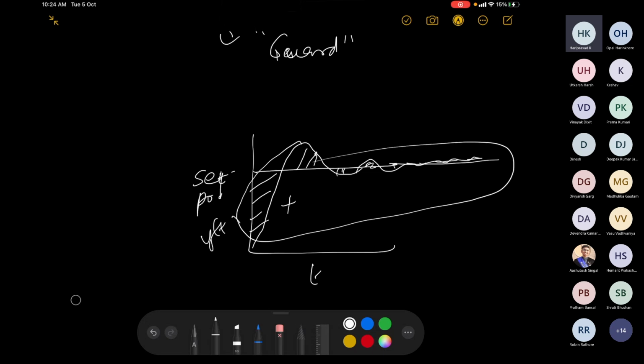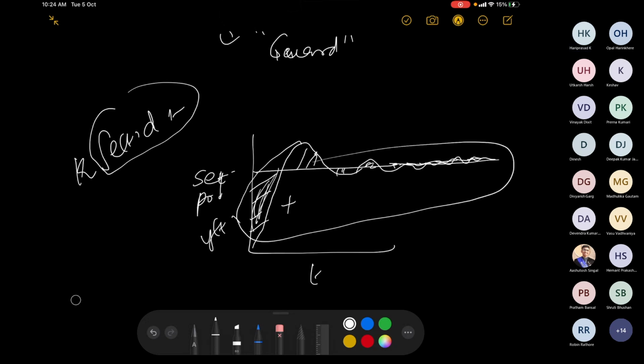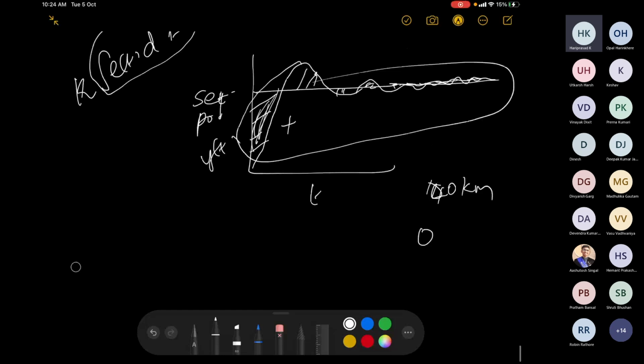So your control action is K times the integral of E of t dt. Of course some part of it cancels out, and it should, because you should not have a large amount of integral action whenever you are close to your set point. Initially, yes, because it's like applying the accelerator. Let's say you are interested in driving the vehicle at 100 kilometers per hour, and you are starting from a traffic signal at 0 km/h.